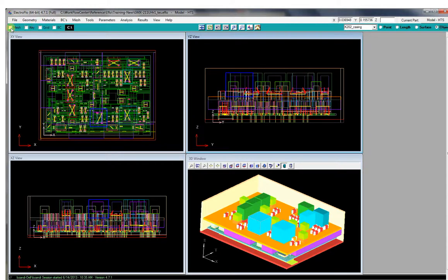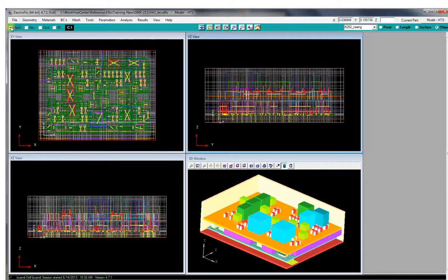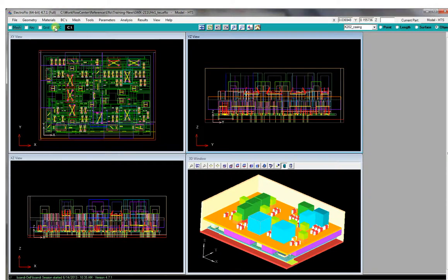Display controls are used to quickly display or hide entities that are not commonly displayed throughout the modeling process. These entities include the mesh, key planes, construction grids, and boundary conditions. To display the mesh, move the mouse pointer to the mesh box, click the mouse left button. To display convection boundary conditions, move the mouse pointer to the BC box, click on convection, and then click apply.